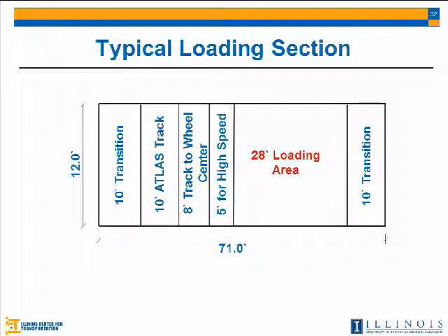What's the main use for PPA? The main use when they came up with PPA is to reduce the aging rate of asphalt mixtures, to minimize the low temperature cracking. So when you use PPA, it does not age as quickly as other mixes. So it retards the oxidation process? Exactly. Supposedly.